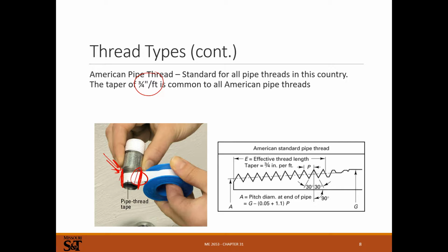There's other methods of sealing pipes where you've got straight threads, and then you'll have sort of a taper down here, and then on the other side, you'll have some kind of another taper, and it will seal on these tapers. So like AN fittings, that's how they seal, and it's usually a nicer sealing method. You don't have to crank down on things as hard, and you don't have to use Teflon tape at all, because the sealing is all on this taper here. You can still damage the fittings on it, but usually they come apart easier and go back together easier, and if they're done right, they don't leak.